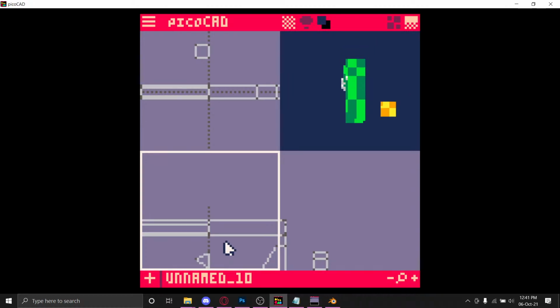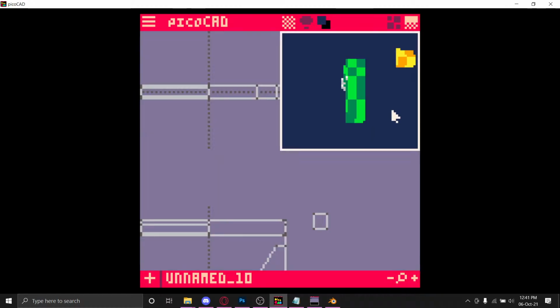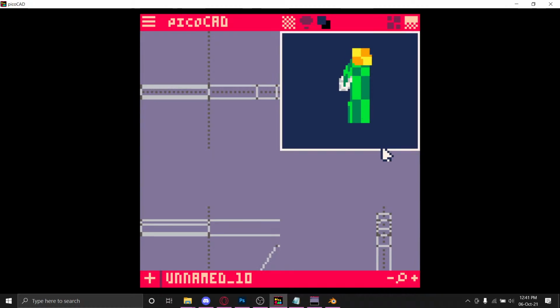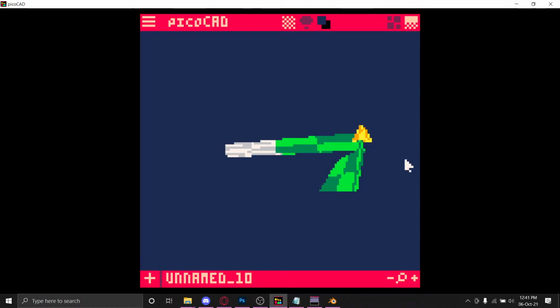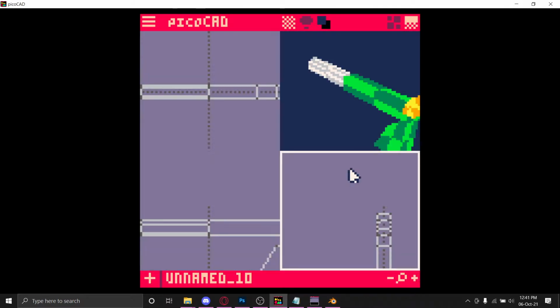And my goal is to move it right over here and select this face and rotate it a bit so that it's facing inwards. Add it like so. And I think it's the wrong side, so I just add it on top over here. Yep. So as you can see, to our gun we added the hammer as well. Here we can texture it in as so.